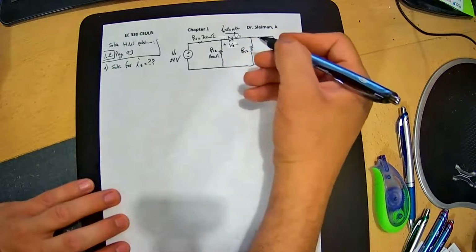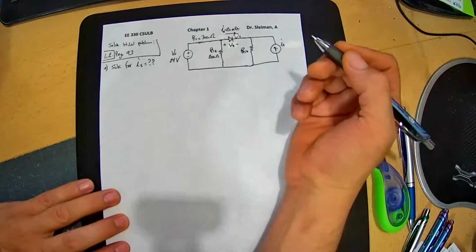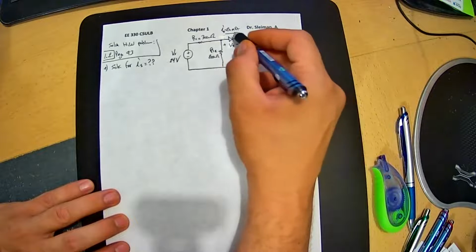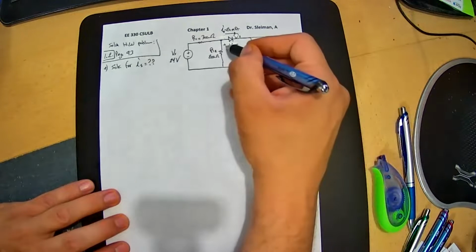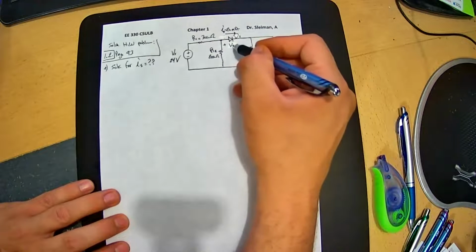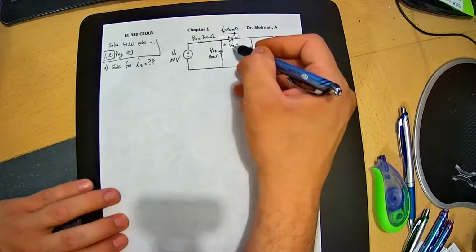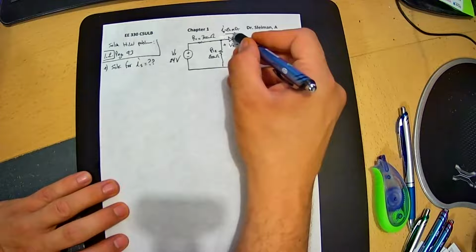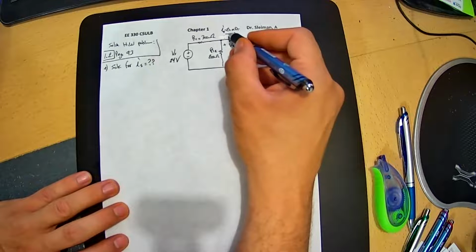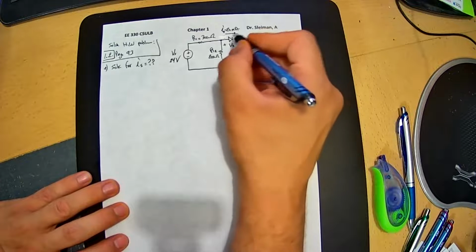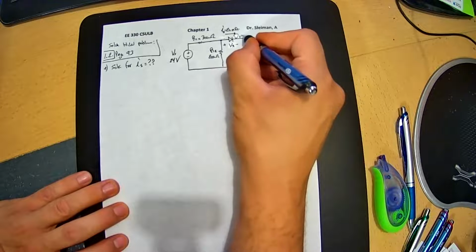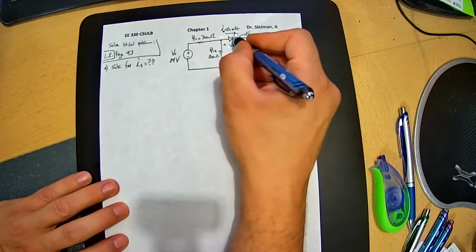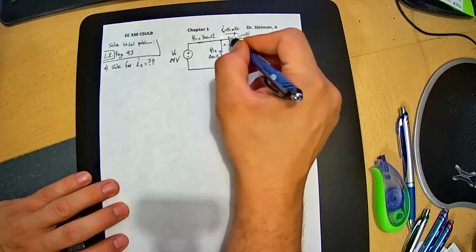That's the voltage across it, because the current is going that way at 20 milliamp. So the voltage will be forward biased in this direction. So if this is forward biased in this direction, that means this is on. That means this is acting as a short circuit. So we have Vx voltage here.